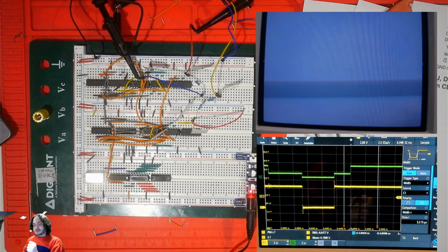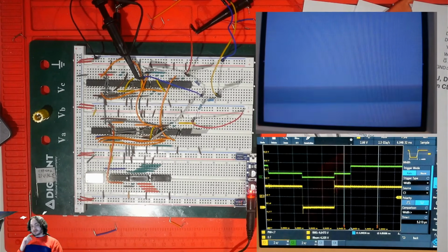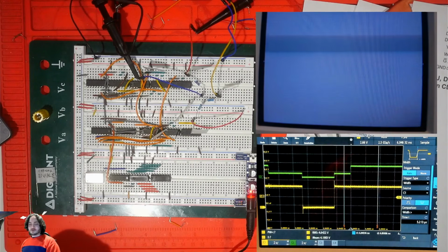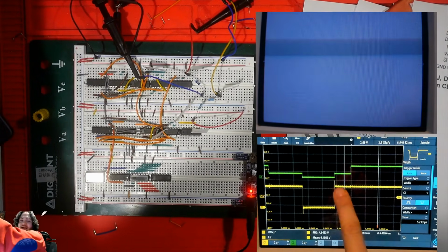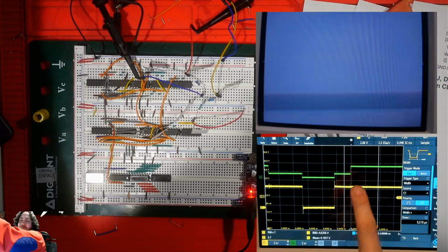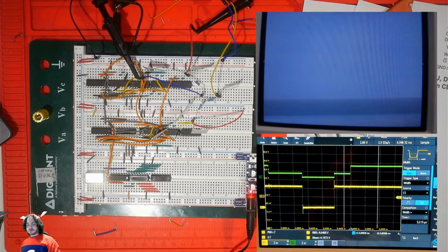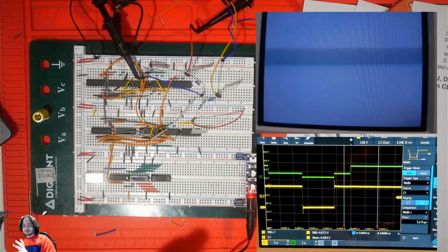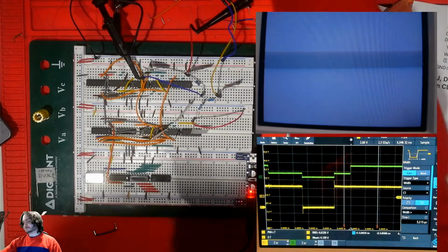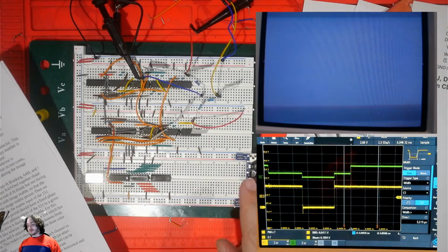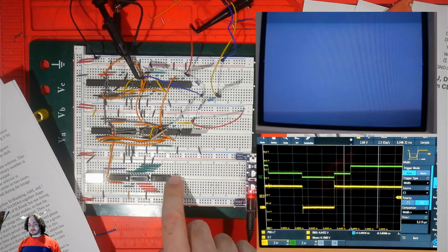In order for the television to meaningfully interpret that phase change, it needs a reference. And that's going to be a fixed phase. So we inject some color phase outside of image enable into this zone, but we also want it to happen during image enable. So first we're going to construct a signal that is going to shape this, essentially, and then we're going to combine that with image enable so that we get a signal that enables the chroma carrier.